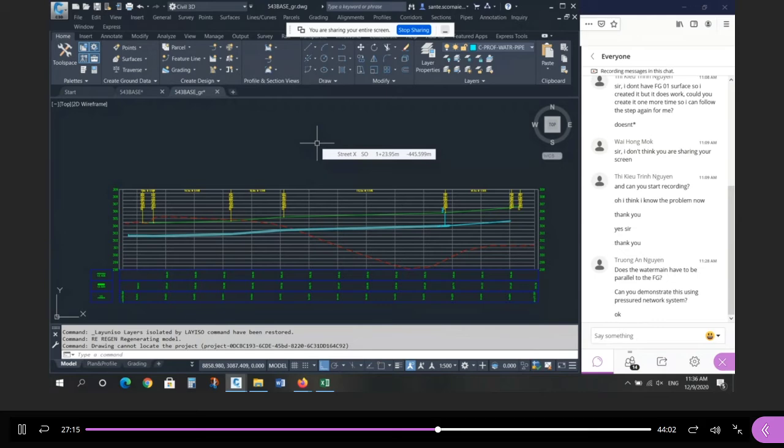With the different consulting firms that I worked with and for subdivision work, this is the preferred method, AutoCAD drafting only. Okay, and that's all I'm going to expect you to be able to do. You could do a pressure pipe this way as well, right? But then you may want to use the pressure network. You can actually do flow analysis using Civil 3D pipe networks with a storm, sanitary, or water main.